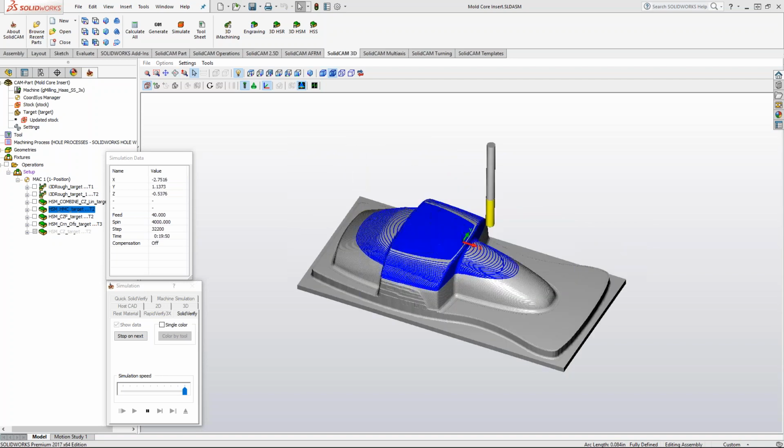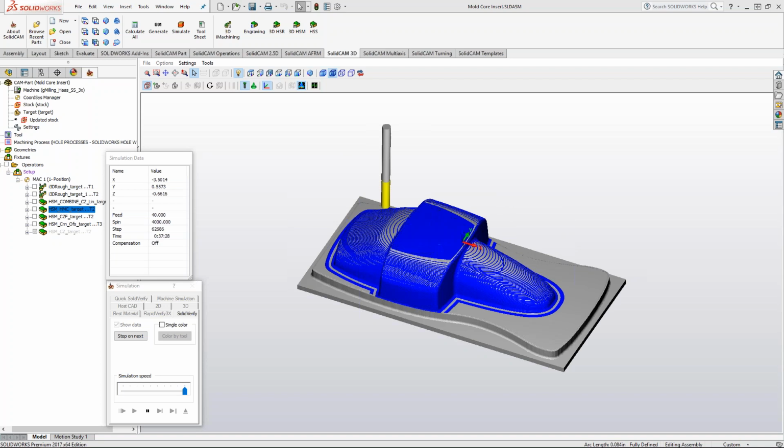Well, most of the tool holders I use for end mills, especially from, let's say, a half on down, are the ER style for finishing. At the time now, we're using a lot in our live cutting the Rego Fix. What is it? Power grip. Power grip. Yep. Yeah, those are really good. They hold the tool more concentric than even the high precision ER collets.